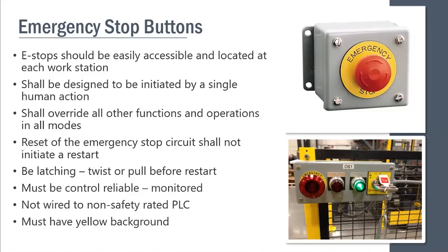As we walk up to a machine and look at a machine, that e-stop should be easily accessible and located wherever the operator is doing his task. For metal working machines, that's typically pretty obvious. For things like conveyors, you may need an e-stop function along the whole line of the conveyor. Again, where operators are working, they need to have immediate proximity to an e-stop.